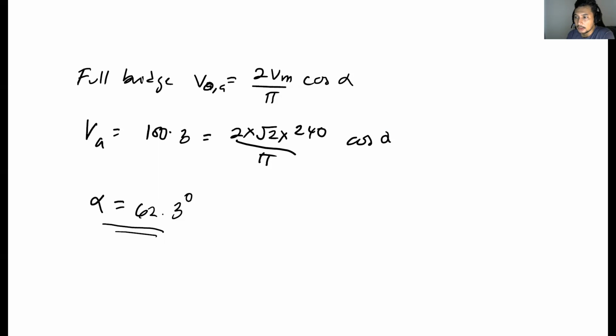This condition depends on the size of the inductor. Usually for the DC motor, the size of the inductor is very large compared to the internal resistance of the armature circuit. So by using that assumption, we assume that the rectifier is operating under CCM.